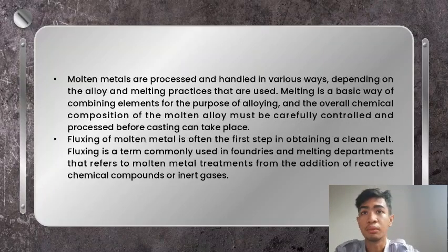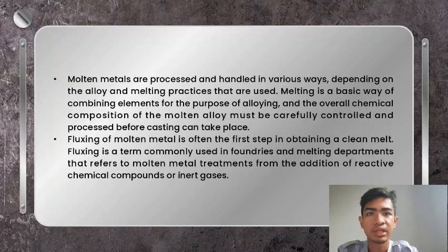And the combination includes removing inclusions, impurities, or dissolved gas from the melt, preventing excessive formation of solid phase inclusions, preventing and/or removing oxide build-up on furnace walls, injecting or distributing alloying constituents. Thus, fluxes are commonly used to some extent with virtually all molten metal operations, in both the foundry and in the production of mill products.